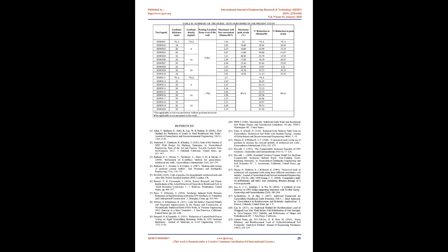Reinforcement strain distribution. Figure 9 shows the reinforcement strain distribution within the geogrid reinforced soil walls without and with geofoam inclusion and footing placed above the reinforced zone. Peak strains were observed to be located towards the face of the wall, following a definite pattern of line of action. The line of action of stress distribution was observed to be deflecting outward along the height of the reinforced soil wall. A maximum peak strain was observed to be up to 24% for the top layer of the geogrid reinforced soil wall without geofoam inclusion. Maximum peak strain is nothing but the maximum of the peak strains obtained for each reinforcement layer.